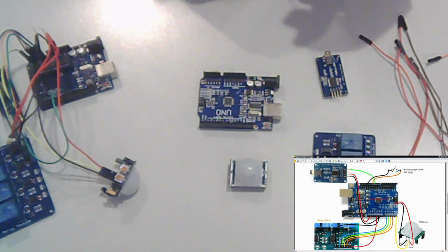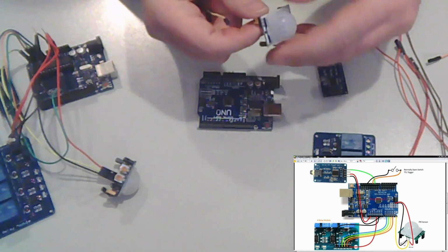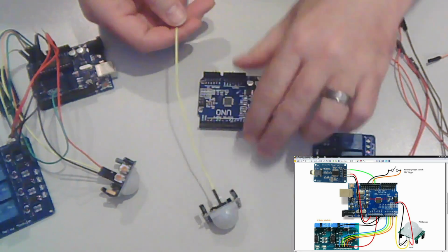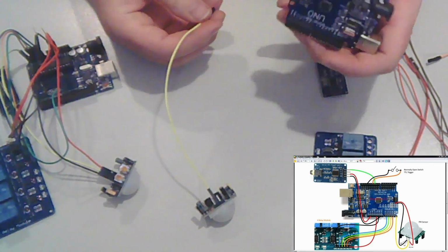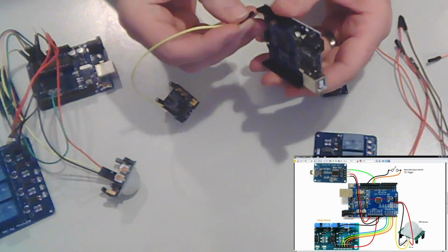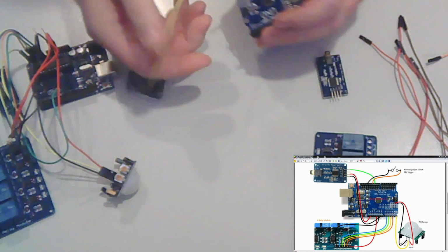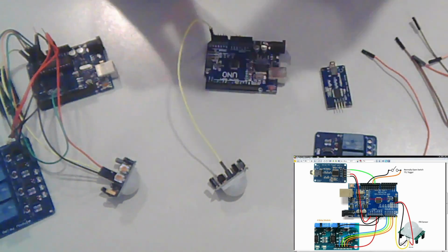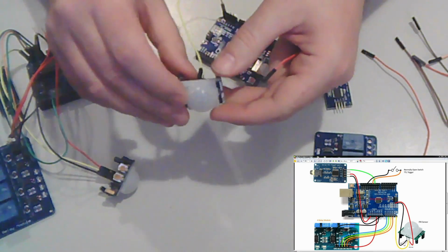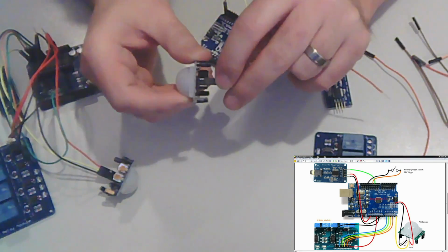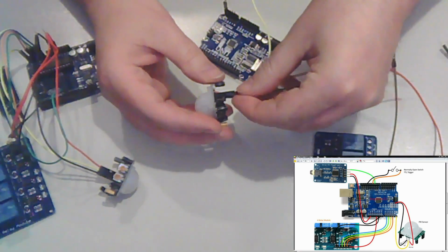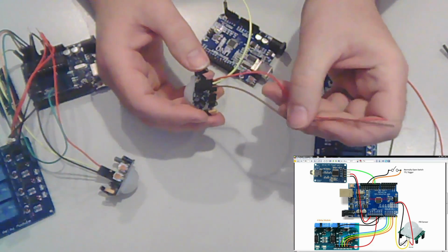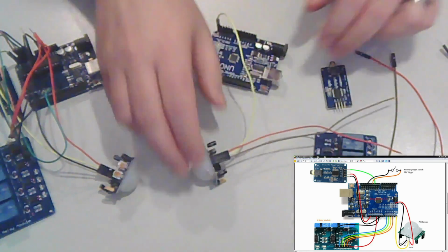For the PIR, pin number 2 is yellow, and that goes to A5 on the Arduino. Done. We can do the power right now on that also. That's pin number 1. The ground wire. And if you recall, we're going to combine those with the other power and grounds from the other components. So the PIR is effectively done.